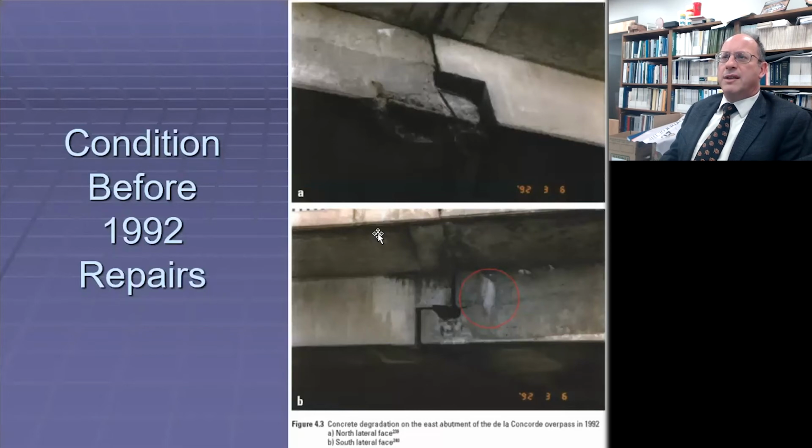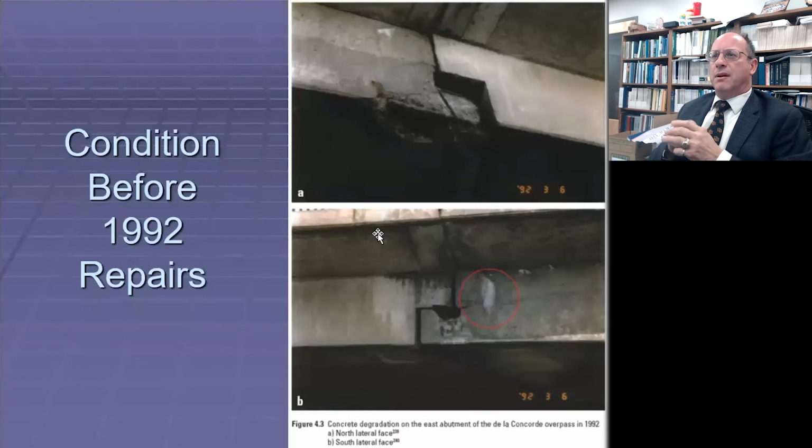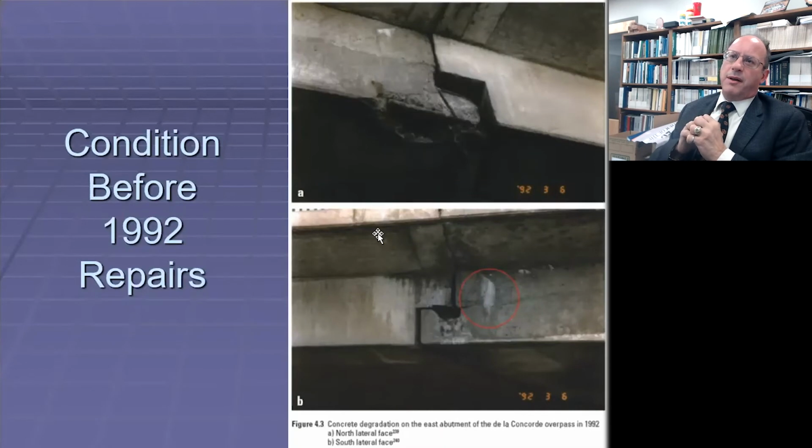If you look at the two ends at the expansion joints, and if you think about what happens with an expansion joint, the part on the right of the top figure and the left of the lower figure is the pre-stressed, and then you have the supports, and you can see that that concrete looks deteriorated. You've got a parallel crack.